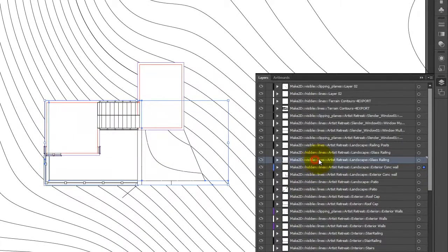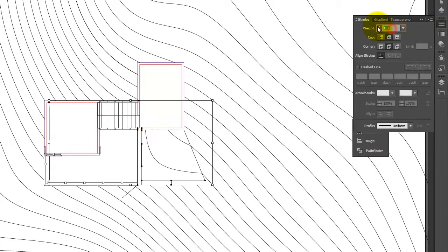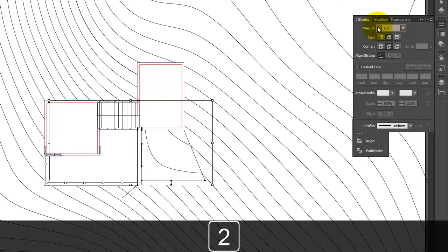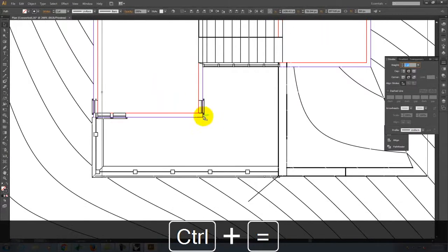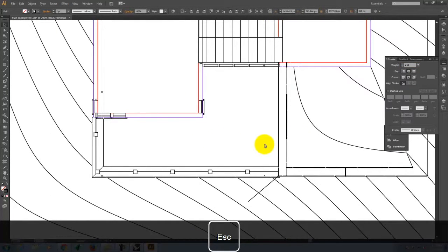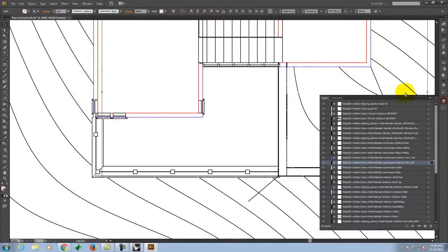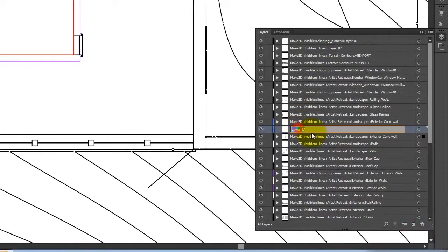Those are visible. Visible here. Let me select those. There we go. So I've got those exterior visible concrete walls, and then I can adjust their weight independently. So maybe those become 2-point lines and are a little bit thicker than some of the others. So the point is that I have a lot more flexibility now with how I'm choosing which lines. And so if I were doing this and setting this up, I would make 2 layers that identify hidden or visible. So we'll start with visible.